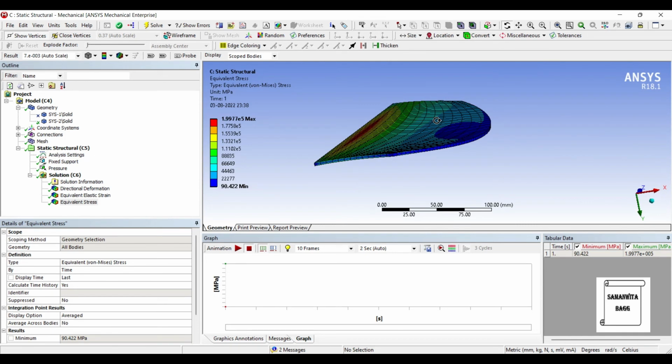that we had started by giving it a thickness of 20 mm. You can reduce it to 5 mm and that should be fine. I have reduced it to 3. You can make it 5 and solve it. So this is how you analyze an object for its topology optimization, and you make it optimum such that the material that you are using is lesser, and when you use lesser material you get better cost for the same product. You can use quality material but less in amount, and also you would have a safer design.